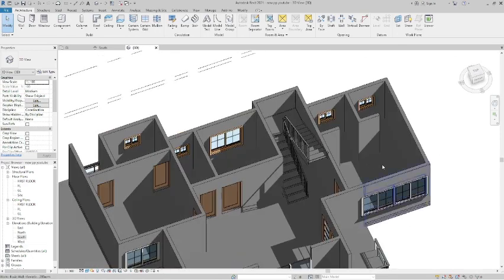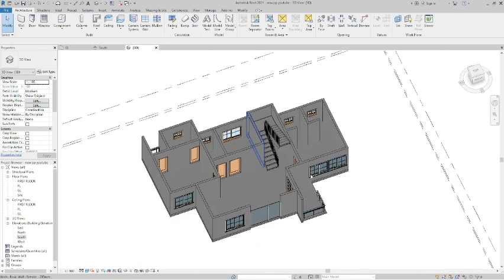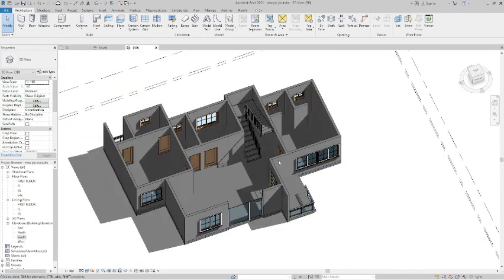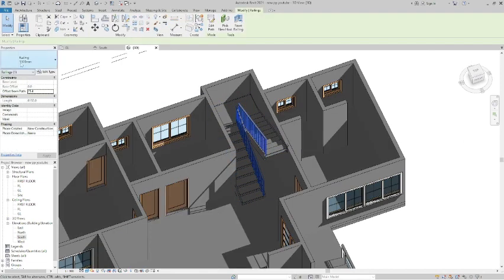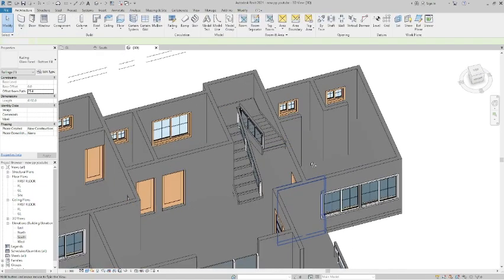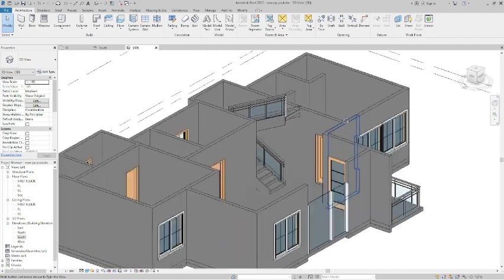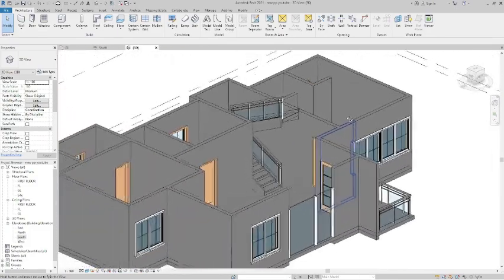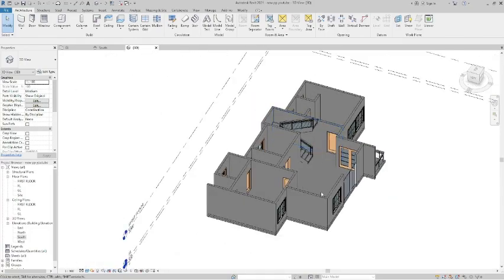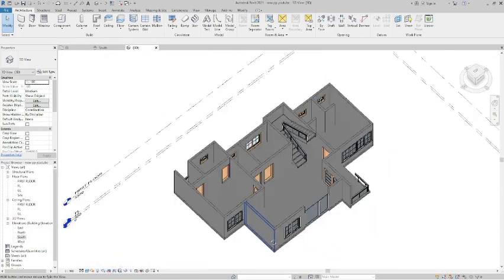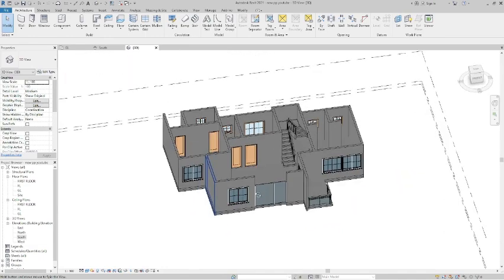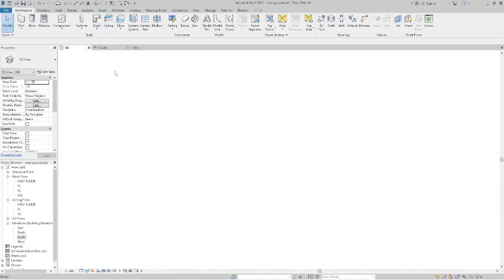So the railing I'll need is here, but I don't like this type of railing. You see what we used here? So I'm going to use the same thing here. So I'll just select the railing, go to the property, change the railing. What we have, the glass panel bottom floor, I'll select that. Okay, so I prefer this one. Okay, so now we have our stairs, we have everything inside, so we can move ahead and insert our components.